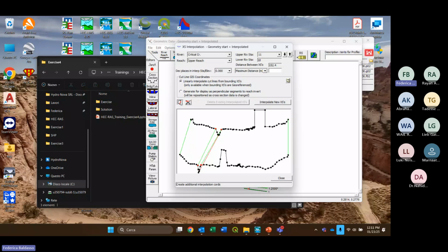So when you click on this button, your mouse will turn into this pencil icon, and when you are like this, you can click starting from the point you want to connect, and drag until you reach the second point you want to connect. Once you are above the point, just release the mouse and you obtain this chord line drawn in your window.